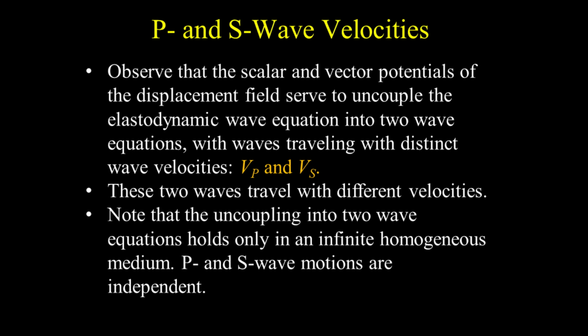Observe that the scalar and vector potentials of the displacement field serve to uncouple the elastodynamic wave equation into two wave equations, with waves traveling with distinct wave velocities, Vp and Vs.